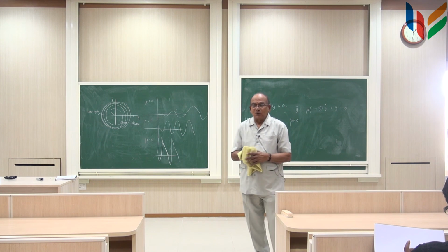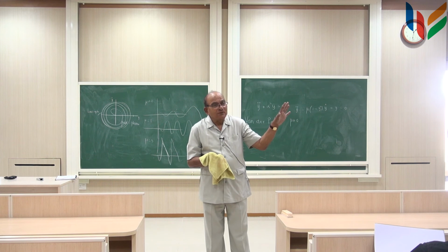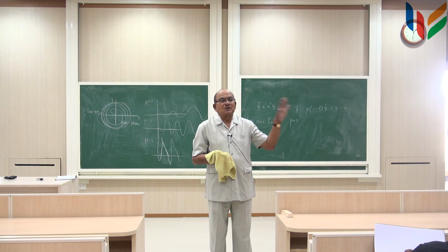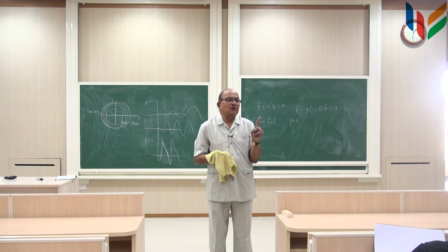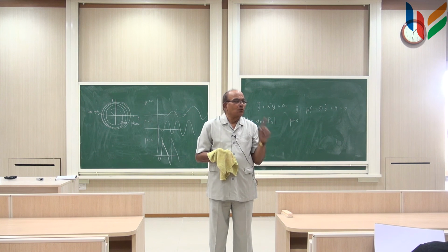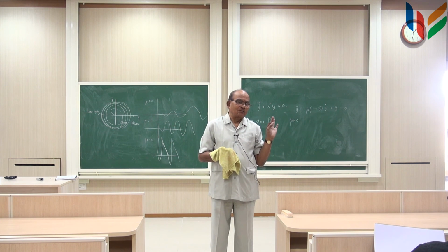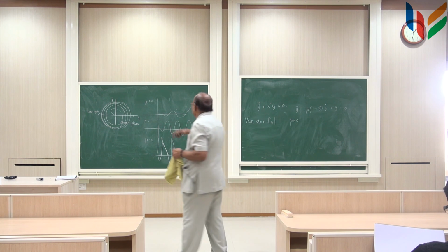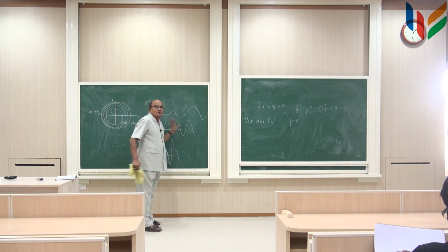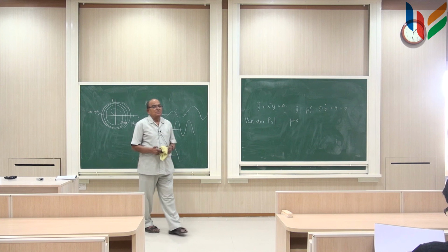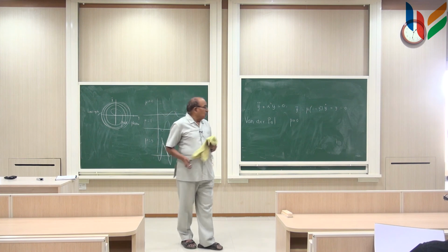So, this is very far away from the actual performance of the oscillator, because that model will never give you the amplitude of the sine wave coming out of this oscillator. It will only tell you the frequency will be this, whereas this analysis will tell you what is the stable amplitude you are able to get for the given value of mu, and so on and so forth.